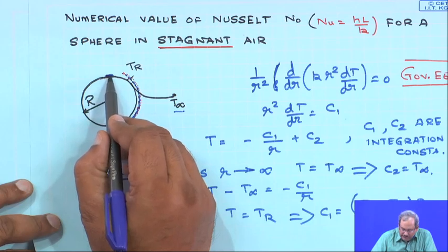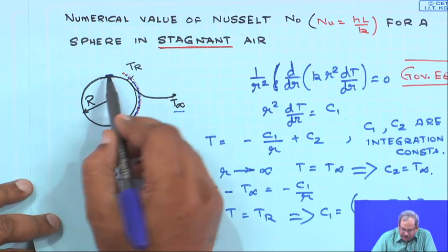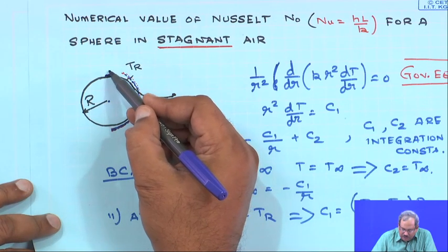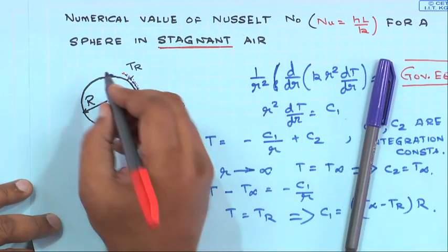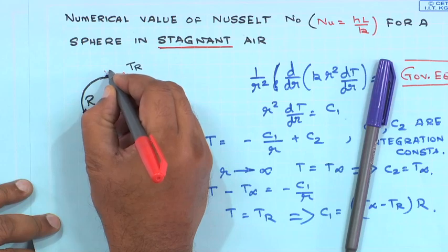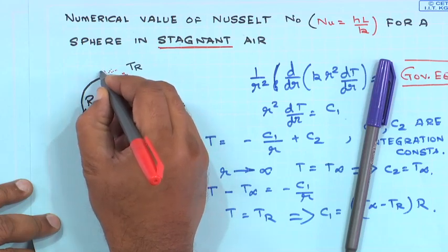So, all the heat transfer through this immobile gas layer must take place by conduction, and on the outside of this gas layer the air is mobile. So, therefore, you can have convection from this immobile layer.